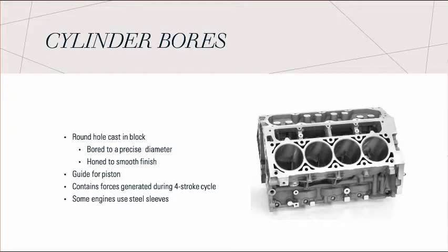Its main functions are to act as a seal against the combustion gases, as well as to prevent lubricant ingression into the combustion chamber. Another key function is to conduct heat away from the piston to the liner, and both these requirements call for minimization of the gap between the ring and the bore.